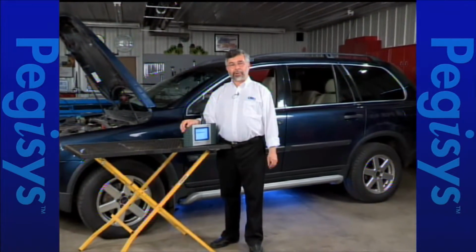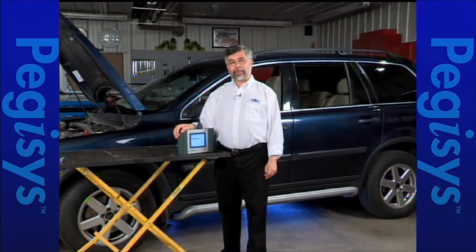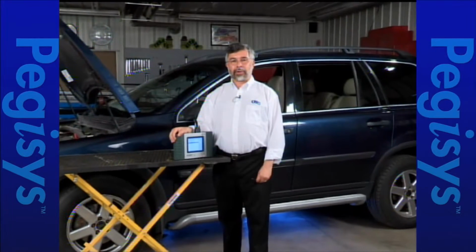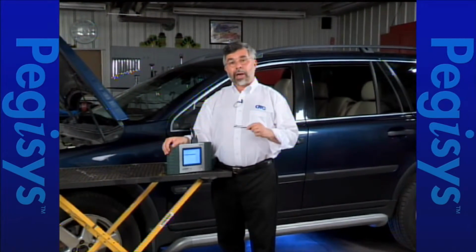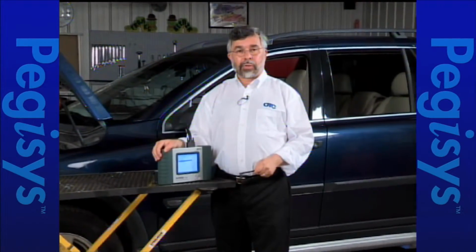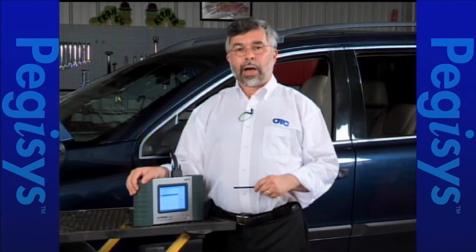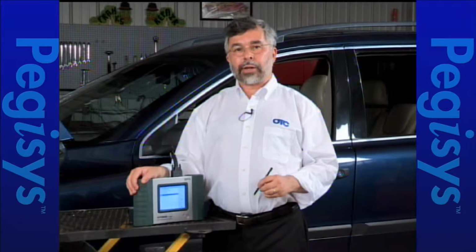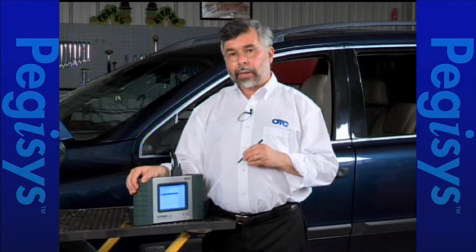This evening, we're going to show you how to do coding. Coding, which is also known as adaptive data or adaptive strategies and/or relearn. We're going to show you how to use your Autobots, Pegisys and Genisys to do coding on several European vehicles. The first vehicle we're going to look at is a Volvo XC90. On the Volvo XC90, I'm going to show you how to do steering angle inclination or steering angle coding.